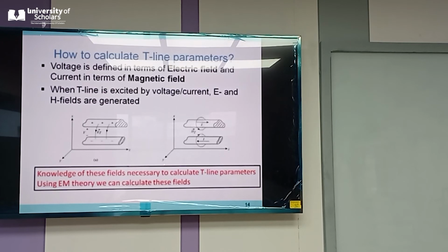What we see as a wire at low frequency and at the circuit level is not just a wire, because it can act as an inductor, it can act as a resistor, it can also act as a capacitor, or in a worse scenario, it can act as a complicated circuit that can be modeled as a combination of resistance, inductance, and capacitance. So these are the lessons learned.